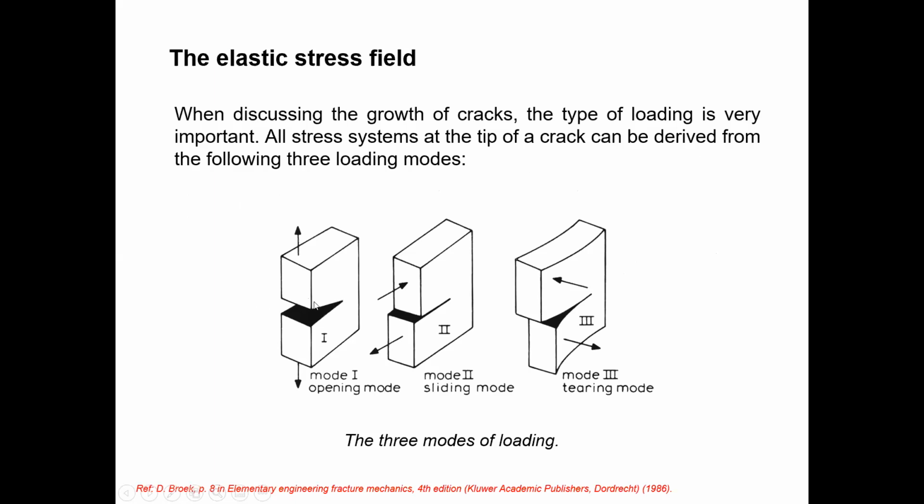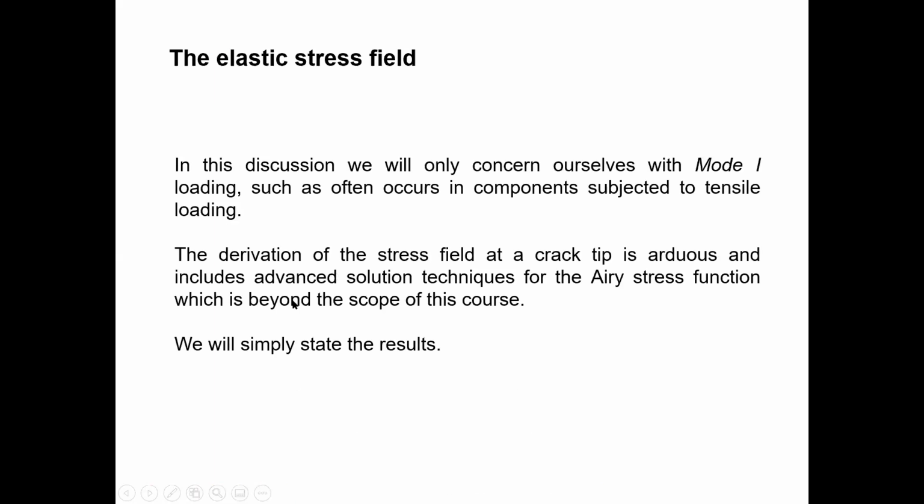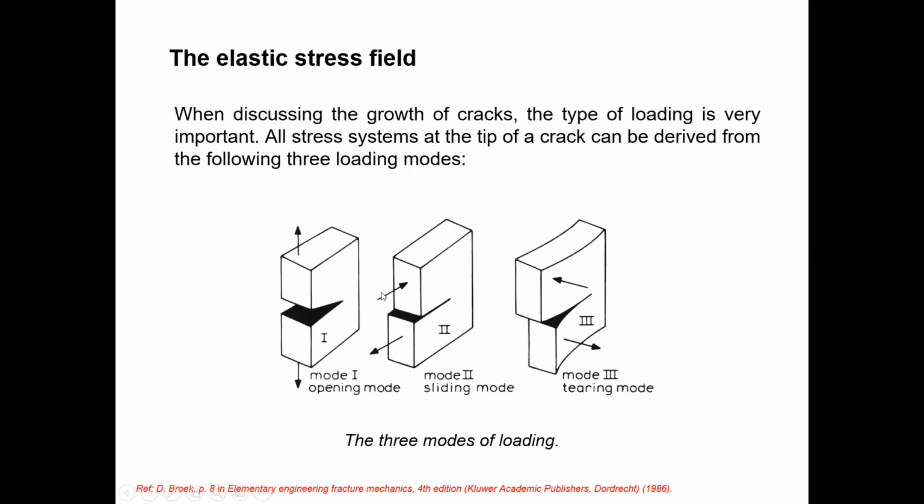You can see the crack can easily propagate to this side. Normally the opening mode will happen with a tensile load. You already know that. The derivation of the stress field at the crack tip: crack tip means, I think you know, somewhere here. It is a high stress concentration point.